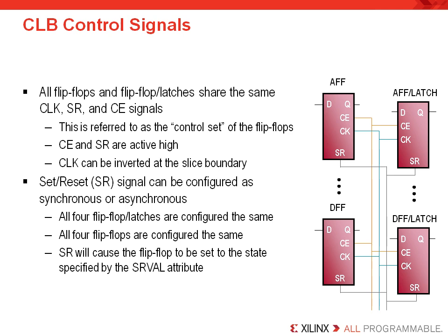All flip-flops and flip-flop latches share the same control signals. The group of associated control signals with a flip-flop is important since only flip-flops that share the same control signals can be grouped into the same slice. This means that if you don't manage the use of your control signals and try to reduce the number of control signals your design has, then you might have trouble getting high device utilization.